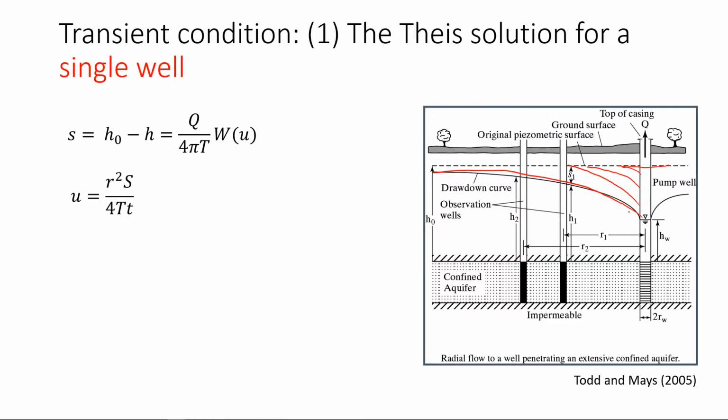That's a pumping test. And why do we need to do this? We need to do this because we know Q, we know S, and we want to estimate T and the storativity. That's why we do a pumping test. But from a pumping test, we can also learn about other things.